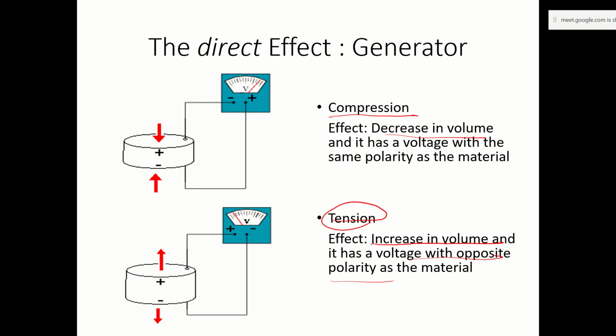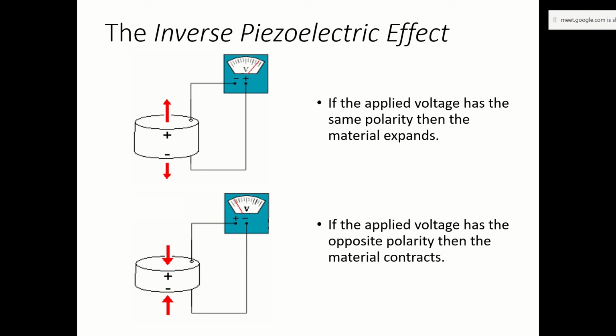Okay, compression, and you also see that when you are compressing, the voltage developed is plus minus, like here. And then you also have, when the applied voltage has the same polarity, the material expands. If the voltage has the opposite polarity, then the material contracts. So this is an inverse piezoelectric effect.